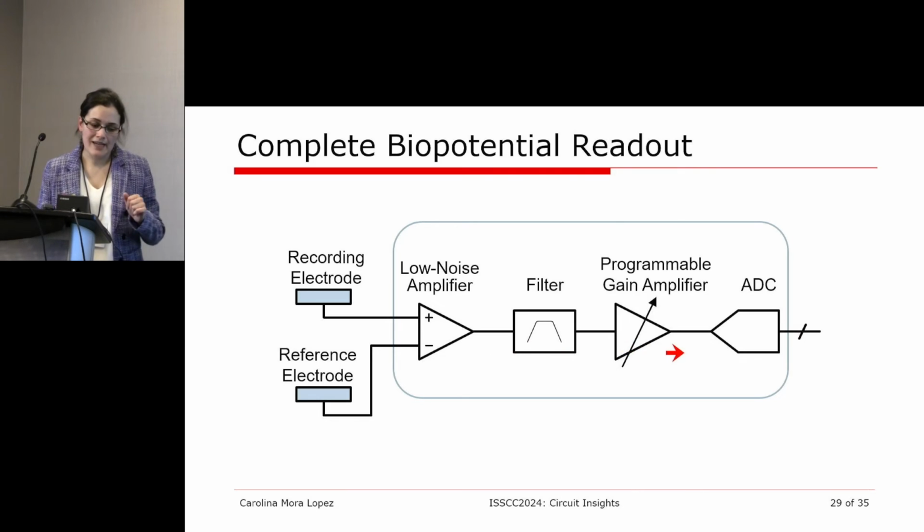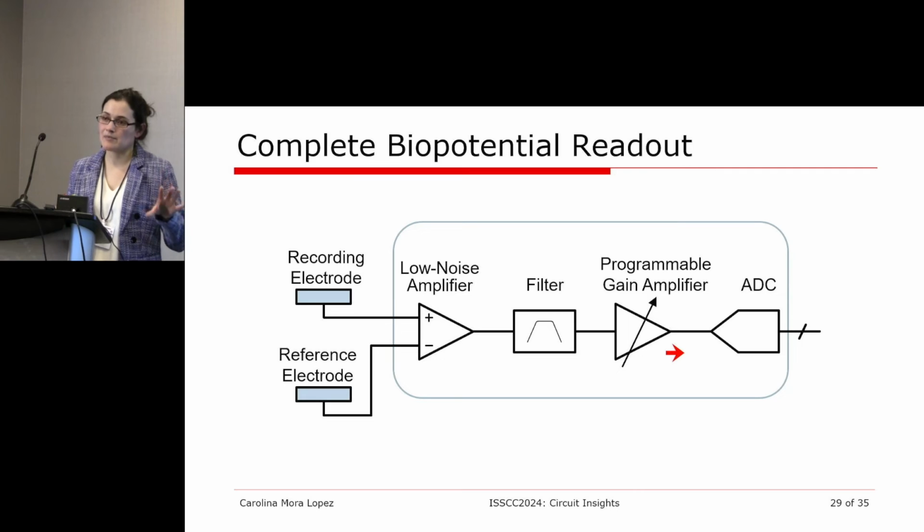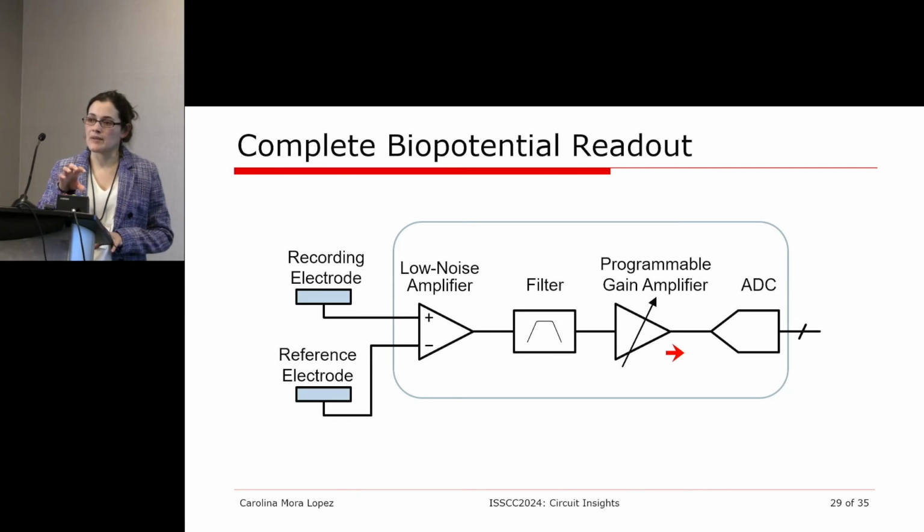So you want to design your ADC in such a way that the quantization noise it adds is not significant, that it remains lower than your other noise sources, but you also don't want to over-design this ADC, because over-designing becomes very expensive in many ways. The area and the power of an ADC are actually exponentially proportional to the number of bits. So adding an extra bit is very expensive in area and power. You just want to have enough, but not more than enough.